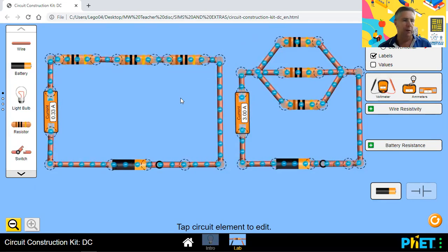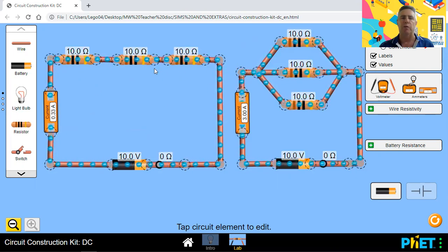Point number 4 is about how we calculate equivalent resistance. We prefer to say equivalent rather than total, because total would include the resistance of the battery, the ammeter, the wires, and everything else. So the equivalent resistance of those 3 resistors, R1, R2, and R3, is what resistor you would need to replace them. So here you simply add up R1 plus R2 plus R3. Let's put the values back. The equivalent resistance of those 3 is actually 30 ohms. That's why 10 volts divided by 30 ohms gives you a current of 0.33.